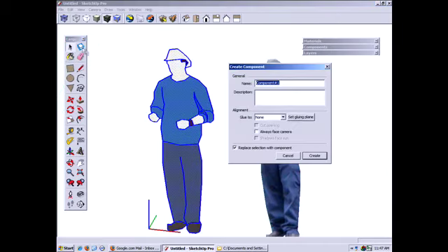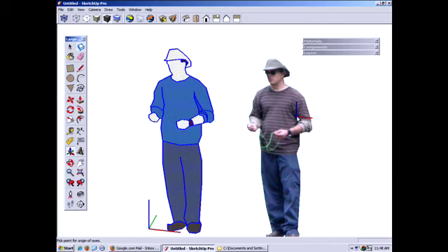Select the geometry, make this a component. Don't worry about naming it. Always face camera. Shadows face sun. That's a good thing generally to have on. I'll show you why. Set gluing plane. You do want to set your own gluing plane. Don't accept the default, which is over here. Even though that's not far away, it's still not at the center. So I'm going to set it, say, right here at these feet.